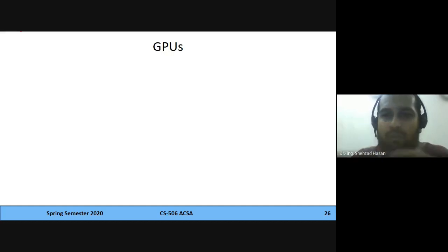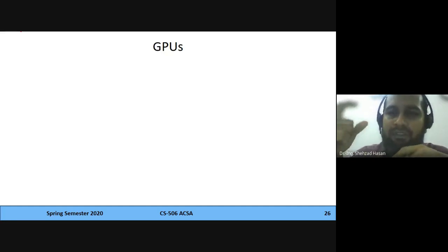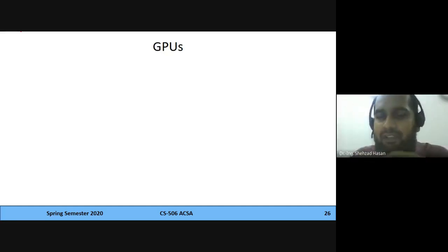That was also the case when we were talking about the adders, the RCA, the ripple carry adder, and the carry skip adder. You were supposed to give me an example which shows the benefit of the carry skip adder. That was the example we did in the class: if you have a number that generates a carry in the first level and ripples it to the last level, keeping on changing the result at each level, then this has the worst case delay.